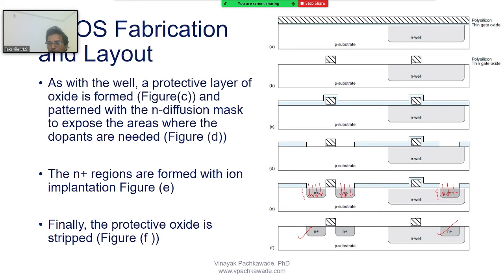Once I got the diffusion process complete, I again etched the remaining oxide, and the final form of the figure is this one. So in this particular slide I got two steps done. I successfully fabricated the gates of the circuit, and the active area of my NMOS, and I also successfully fabricated the body contact of my N-well, which is the body of the PMOS, right?